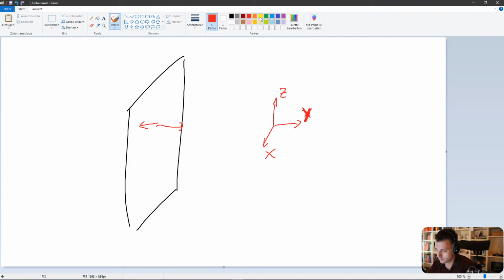And that's where a lot of people get stuck. So we have our DOF 1, 2, 3, 4, 5, 6. Which one should be constrained so that we have no y direction movement? The first one, which is obvious, is the y translational, so that has to be fixed, right?